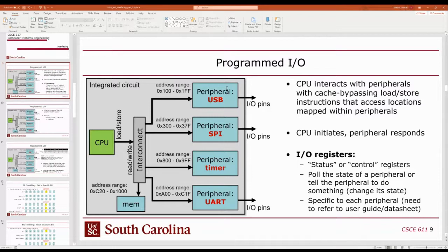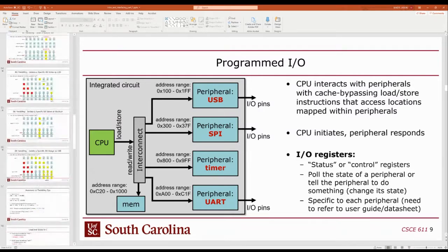But the physical interrupt itself would still happen in a wire between the wireless radio, or well, the radio and protocol stack, which would all be bundled together as the Bluetooth interface, right? That would be part of the system on chip. It would be one of these blue boxes, and the black wire here would, instead of an I/O pin, be an antenna. But a Bluetooth packet would come in, hit the interface, and then the interface would still just use a regular wire to interrupt the CPU. So yeah, that's how a wireless interface would work.